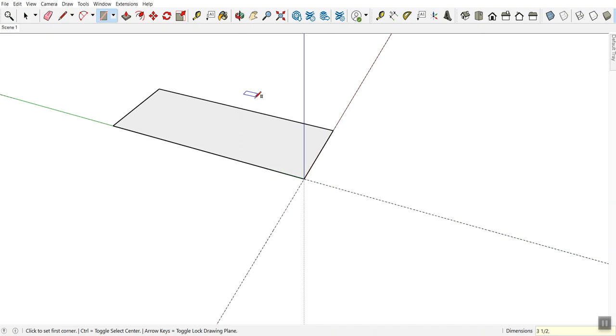And this is probably the biggest thing about SketchUp that people have to get used to: in dimensioning of just about everything, it's always a space and then a small x, like 3.5 by 3.5 is 3.5 space x 3.5. But in SketchUp, when you're creating a new component and making dimensions, you have to put a comma between them.